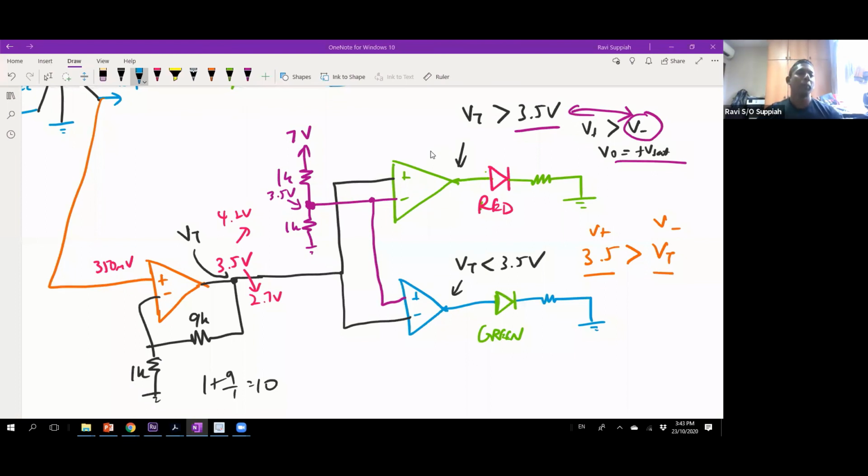Okay, so the resistor value depends on several factors, correct? Again, there is no information or guideline on what is the power supply to the op-amp. So if it's plus minus 5 volt, then you say this is 5 volt, and you can choose a resistor that matches the current limit of the LED. It all depends on the characteristic of the LED, which determines the current limiting resistor you should use. Many times you will use maybe 560 ohm, sometimes they use 180 ohm. So it all depends on that.